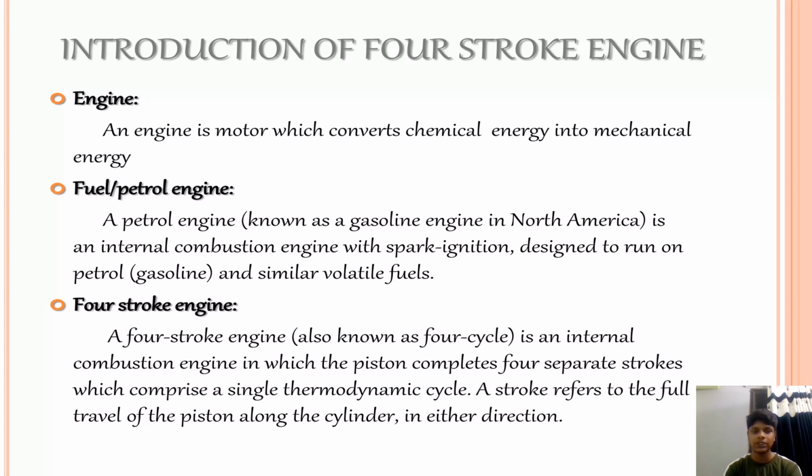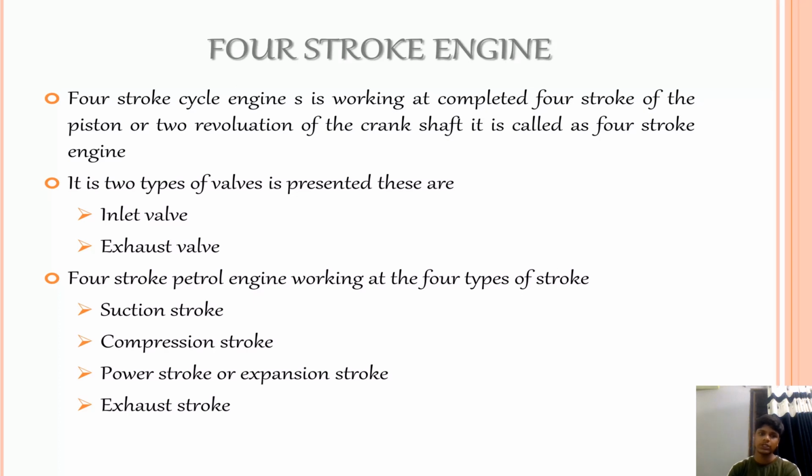Next, four-stroke engine. A four-stroke engine, also known as four-cycle, is an internal combustion engine in which the piston completes four separate strokes, which comprise a single thermodynamic cycle. A stroke refers to the travel of the piston along the cylinder in either direction. In a four-stroke engine cycle, the engine completes four strokes of a piston in two revolutions of a crankshaft. It is called a four-stroke engine.